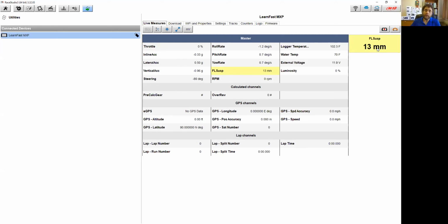And if this is the suspension sensor, when the car's at ride height, that value is going to be somewhere in the middle of its range. So if Roger picks somewhere in the middle, let's put it about there. Let's say that's ride height sitting on the scale pads. Perfect. We can go, and remember this one we picked auto calibrate, different than the previous two.